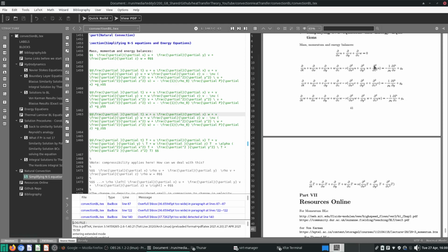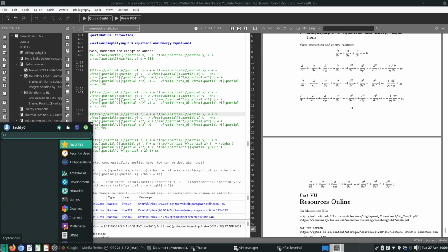Of course, remember these actually have the assumption of incompressibility, and basically your properties do not really change much in the fluid. Now we learned from forced convection that's not always the case. Your viscosity can change, your thermal conductivity can change. To make this set of equations work, you assume an average value of kinematic viscosity, density, and all of these are evaluated at a temperature called the film temperature, where the film temperature is the average of the fluid temperature and the surface temperature.